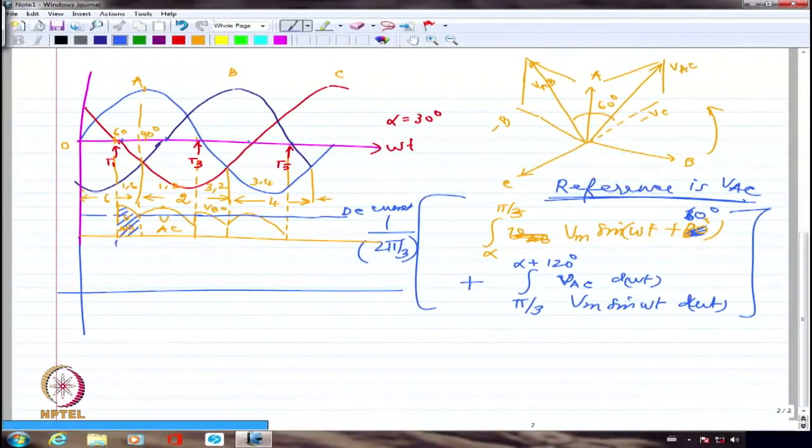Here device number 1 is conducting. So I am going to have clearly A phase current coming up as positive until here. This is A phase current, and please note it is for 120 degrees, no doubt. This is A phase current whenever 1 is conducting. And if I try to look at the other side of the current, wherever 4 is conducting, this is going to be 4, whereas this is going to be 1. And in between I have only 30 degrees, not 60 degrees.